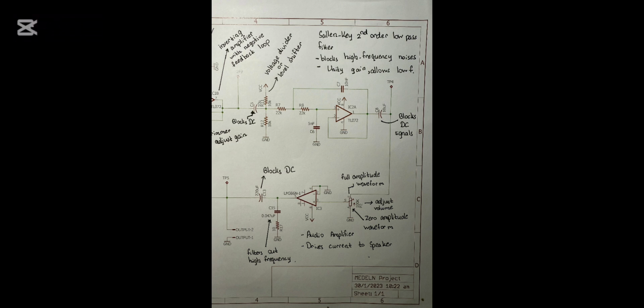In stage 4, the signal waveform passes through the coupling capacitor to filter out the DC signal. Hence, it enters the third IC, LM386N, which is the audio amplifier that drives the speaker. The function of this stage is to power up the waveform to be strong enough to drive the speaker. The IC works in single supply mode internally, so we don't need to provide it with any voltage. It is the only op-amp that drives current to power up the speaker.